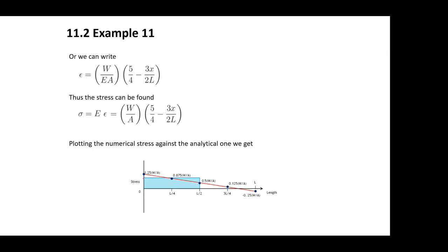So the stress and the strain is going to be constant here and constant here, whereas the one element shape function will try to interpolate the stresses as a linear variation. It's going to try to match a line to this point, this point, this point, and this point. So this is a step-like function, right? And you are trying to draw a line that can pass through these 4 points. The finite element is not going to be able to do that.